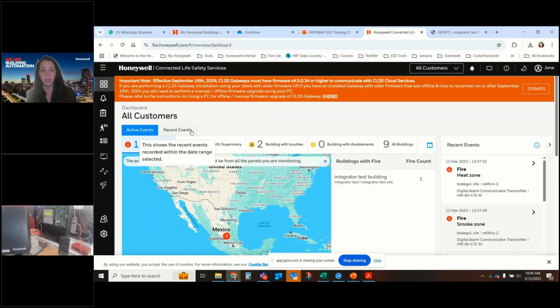The pathway is for one panel, remember, and you can use it in Firelight, Silent Knight, everyone that has a contact ID or DACT card, but also you can use it in any other panel. It's universal as long as the communicator of that panel is installed.